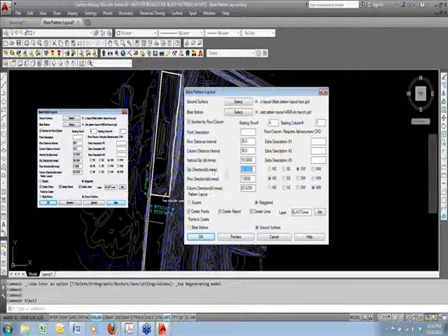The dip direction, now this is important. You must put the number in between the letters. So I'm going to match this window over here. I'm going south 96 degrees west for the dip of those. That's the dip of the hole at 10 degrees. The row direction, I want to go starting here, my first hole, I want to go up to the northeast. So that's north 7 degrees east. The column direction, and this is why I labeled the bearing beforehand. Column is just going to be north 82 degrees west going that way.